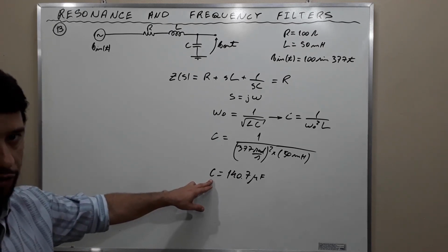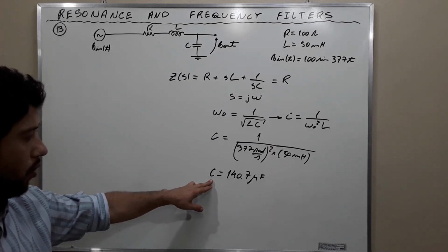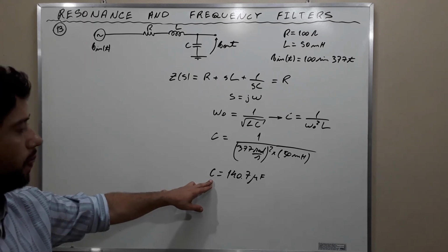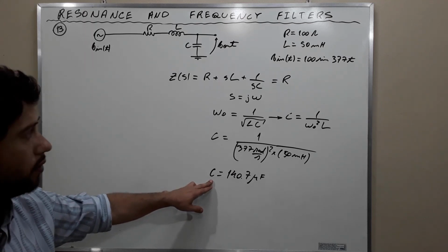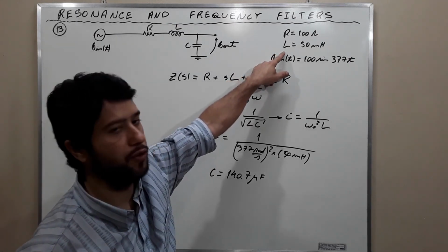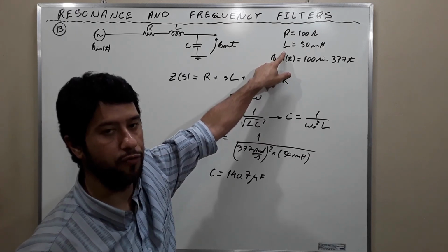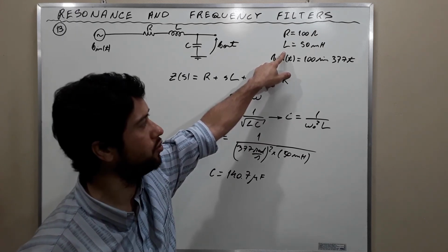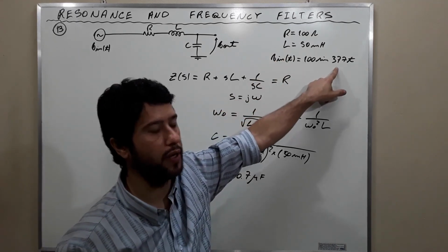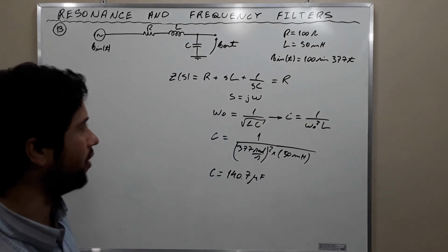This capacitor, pay attention, this capacitor, 140.7 microfarad, will resonate with this inductor, 50 millihenry, precisely at the frequency of the power source, at the frequency of the power supply, which is 377 radians per second, okay?